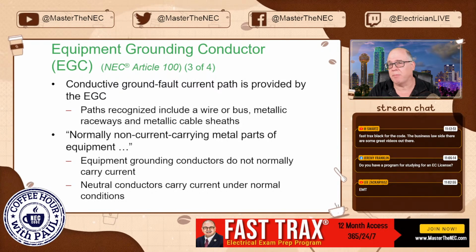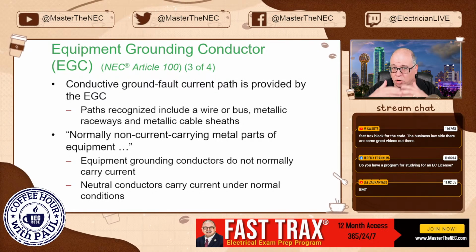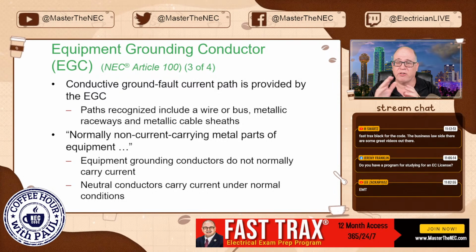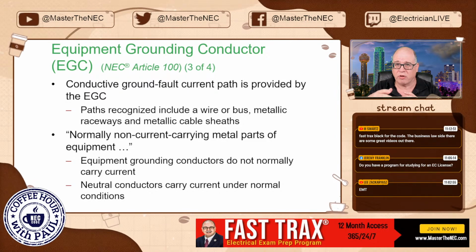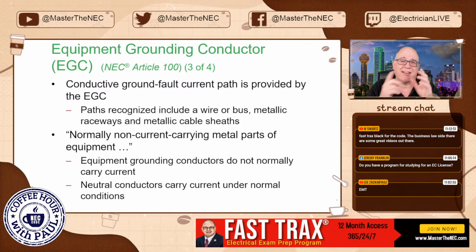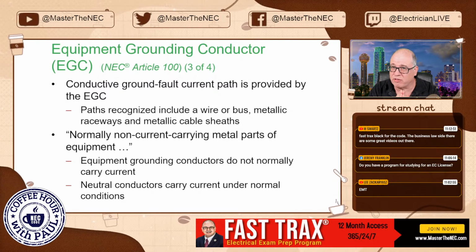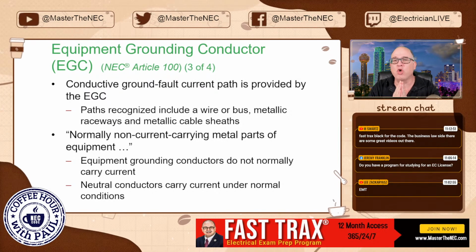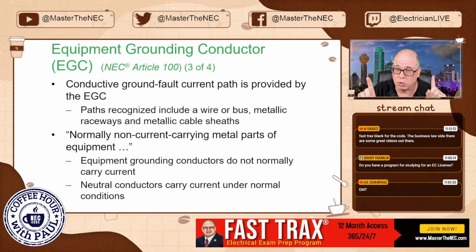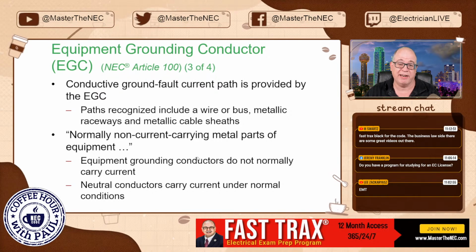With MC cable, you don't use the metal sheathing as an equipment grounding conductor unless you're using something like a smart ground product, which was specifically designed for that, and you can't go past 6 gauge conductors. That's where an MC actually acts like an AC cable, where you can use the armor. But that only applies to a specialty-made type of MC, not normal MC. Yes, it bonds, and the armor is used for bonding to meet that rule, but it's not for the equipment grounding conductor. That's why you have the equipment grounding conductor in there, right?